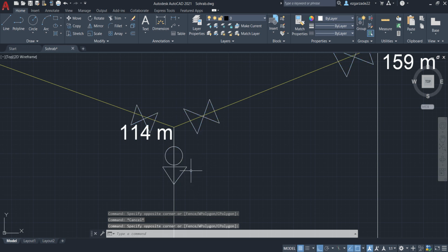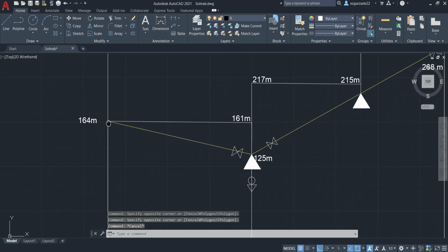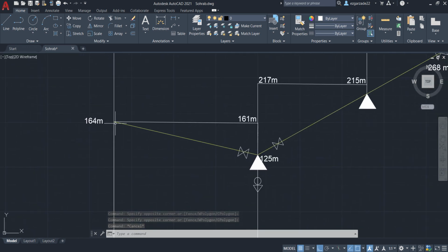It will flow through this pipe to the drainage valve and empty this line. I didn't place one here because it's an inlet. It's already open to the air, and I don't need any check valves here because it's already open. In case of emergency, if I open this and this, there will not be any vacuum pressure here to stop the water from draining out.